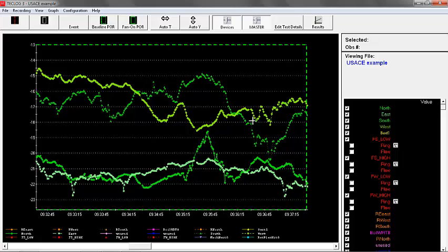So we can see we have quite a bit of scatter. The reason there's such a difference between the upper 2 lines and the lower 2 lines is this building was on a slope where the lower level was two floors lower than the main level. 2 of the outside references were going out the main level, the grade level on the front of the building, and 2 going out on the lower back level.